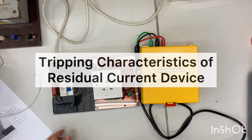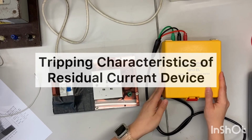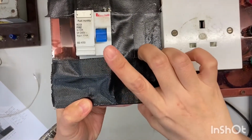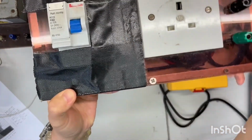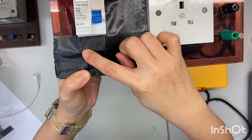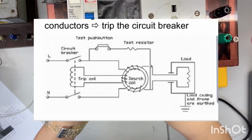The second stage of this experiment is to test the tripping characteristics of the residual current device. This is the residual current device that we are going to test. And there are two conductors connecting to and out of the RCD. It is because a residual current device will monitor the instantaneous current flowing along not only the line but also the neutral conductors. You may refer to this circuit diagram for the wiring connections.